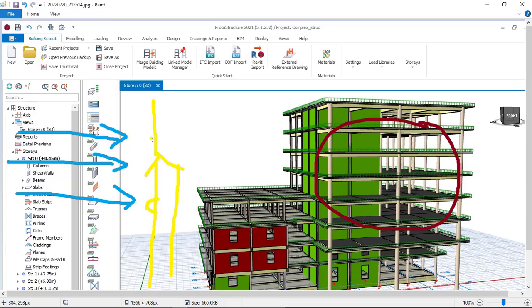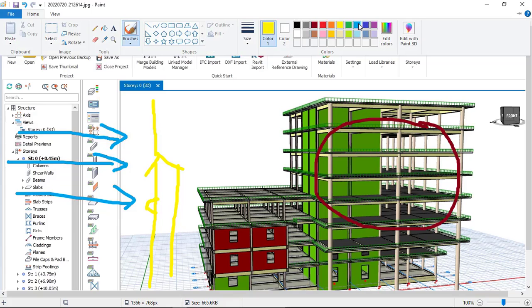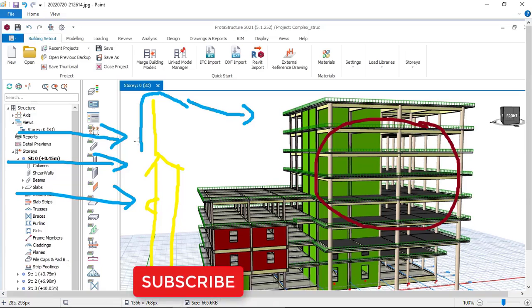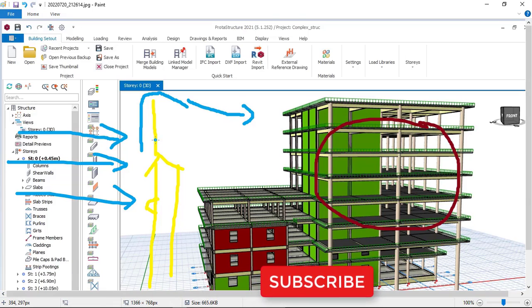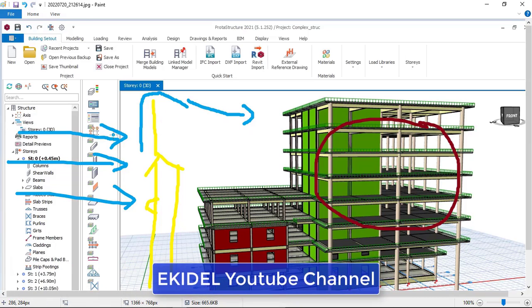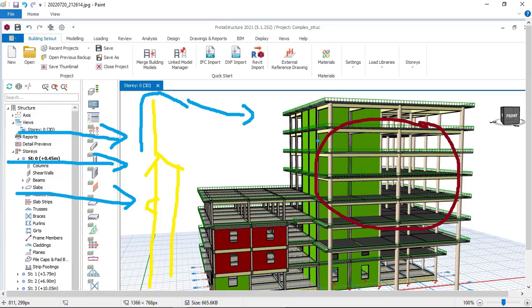And once it breaks, because it will hit this structure, it will now go upward like this. Some will now have to divert. So it will not divert before it begins to hit your structure. So first of all, this obstacle or this building or this tree has stopped at least some of the wind speed percentage from hitting your structure directly. So let me say what was coming to hit this structure was 100% of the wind speed, but with this obstacle found in this place, what is now diverted into your building to hit your structure is just 25%.